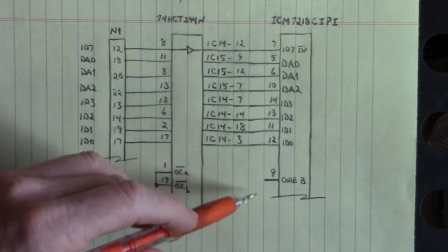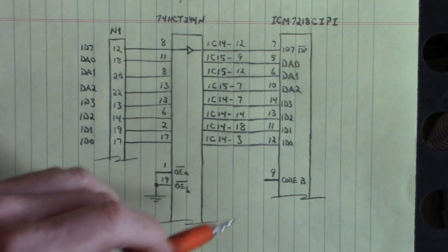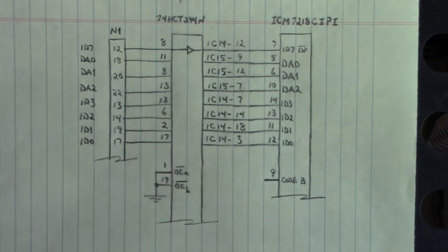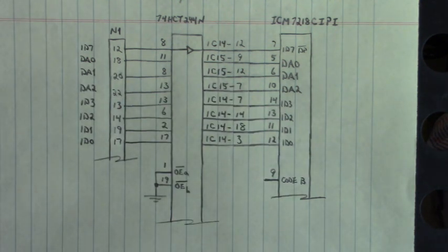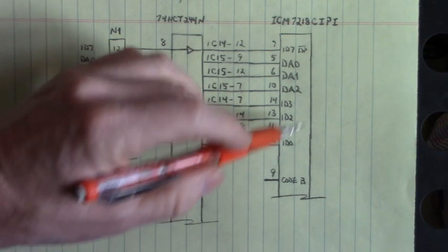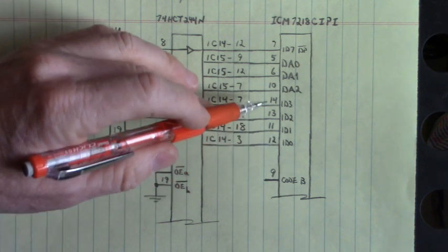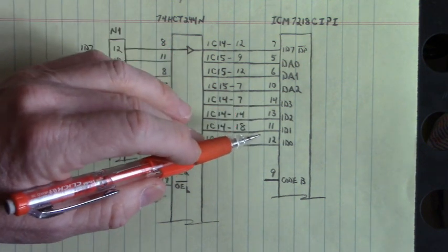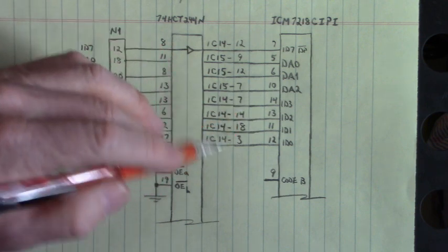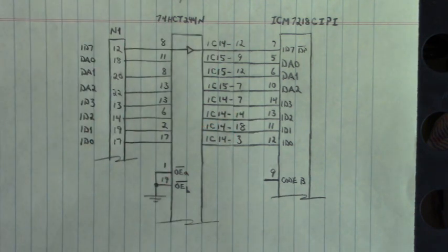If pin 9 is tied low, then that device is in shutdown mode, turned off. In our case, we are sending binary coded decimal out to the 7-segment displays based upon whether we have 0, 0, 0, 0 or 1, 1, 1, 1 and all the states in between.